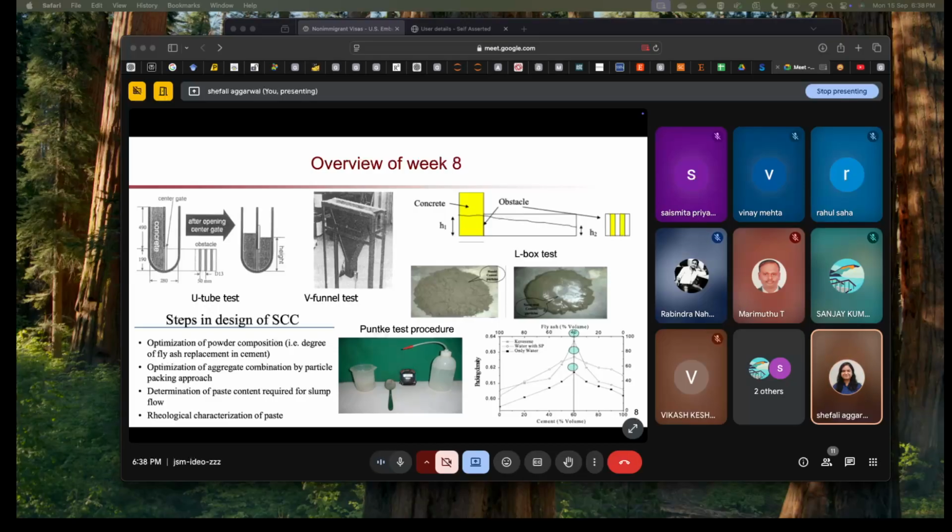The water which is in excess of the voids should appear on the surface. Whatever water is required for hydration should mix fully, and the remaining extra water should come up on the surface of the mix, which will tell us about the saturation limit